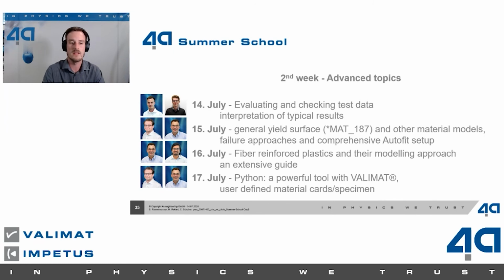This will be quite important for the next sessions, because just with correctly evaluated test data, you can get good material cards. How we generate these material cards, you will see tomorrow from my colleagues Peter Reithofer and Benjamin Hirschmann. They will generate a MAT 187 material card, and for sure they will show you other material models.